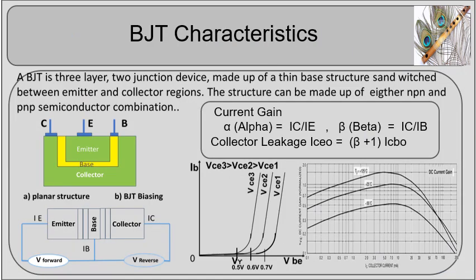Conceptually, a bipolar junction transistor is made of two oppositely connected series diodes. The heavily doped emitter base junction is forward biased and emits carriers. The lightly doped, reverse biased collector base junction collects them. The BJT acts as a non-ideal constant current source. The base current is magnified by beta times and creates the collector current. The BJT has inherent built-in internal feedback and is represented by the early effect. The BJT current gain varies and depends on operating conditions like temperature, collector emitter voltage and current.